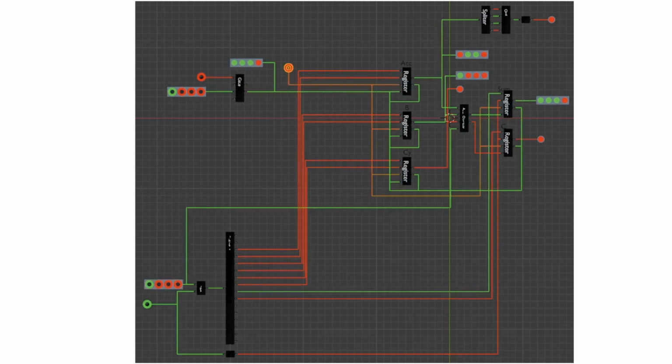That means, first we read the value from sum and write it to the bus. From here it is written to the ACC. The same thing now happens with the result in C, which is written to CY. The ADD instruction is now complete. You can now test further instructions in the same or a similar way. But we'll only do this in the next part.